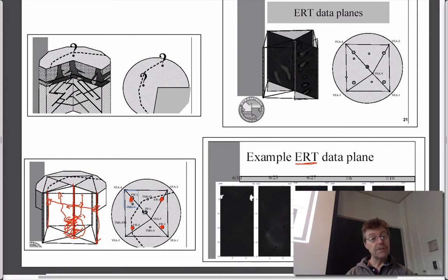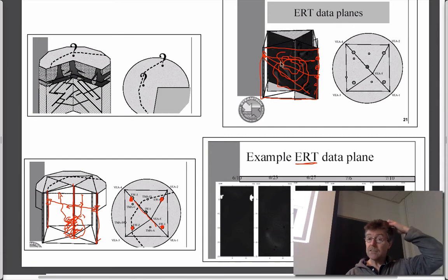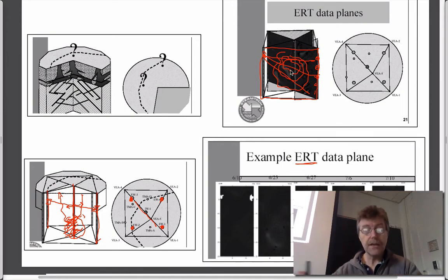It's shooting across here, but it's going to identify every point really only within this plane, because it can only shoot along this plane. Everywhere along this plane, which you can't see very well here, it would produce a little contour map of the electrical resistivity or conductivity by shooting from a source here to all of these sensors. Maybe you'd have 10 sensors in this hole and 10 in this hole to get this conductivity map. As you look at the conductivity in time lapse, day 1, day 5, day 20, day 100, if it's changing and you have a relationship between the resistivity of the ground with DNAPL and without DNAPL, then you can plot how it gets remediated as a function of time.